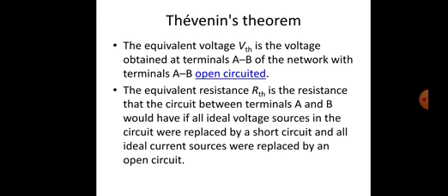It means the theorem applies for AC in exactly the same way as DC, except that resistances are generalized to impedance. Thevenin's theorem and its dual, Norton's theorem, are widely used to make circuit analysis simpler and to study a circuit's initial condition and steady state response.